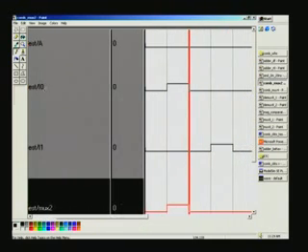So I0 and I1, just have a look. I0 is applied here and I1 is applied here. Now let us see, output must reflect either I0 or I1 depending upon the select control A, and here this A is 0 in this position, and that means we are going to select I0, not the I1.